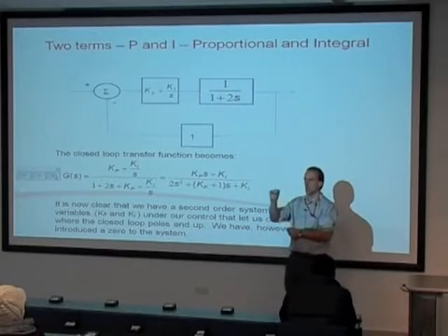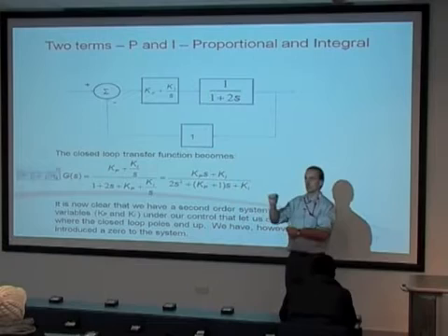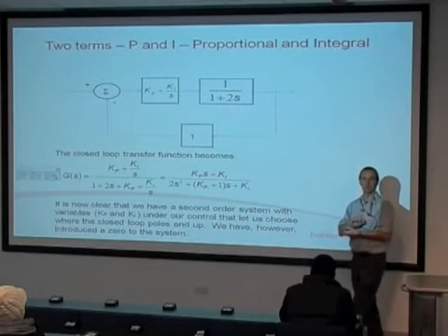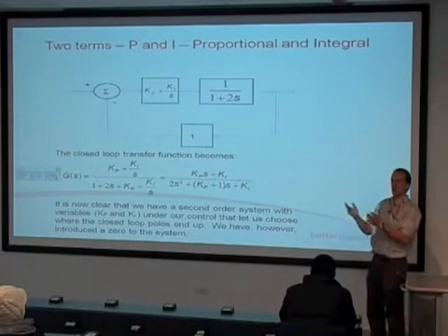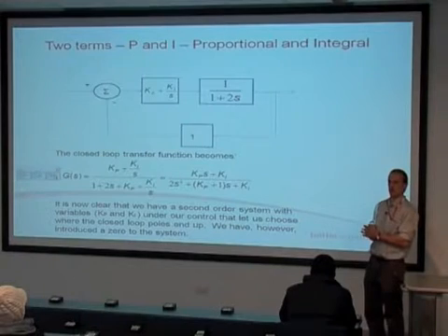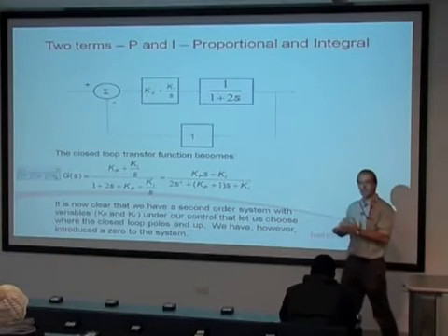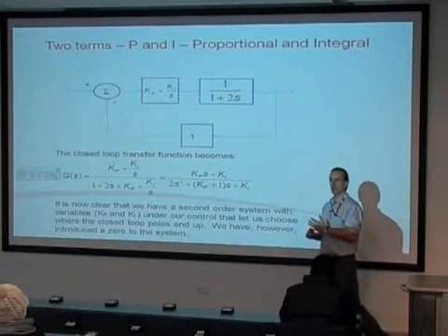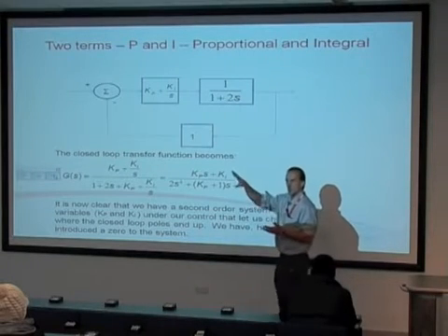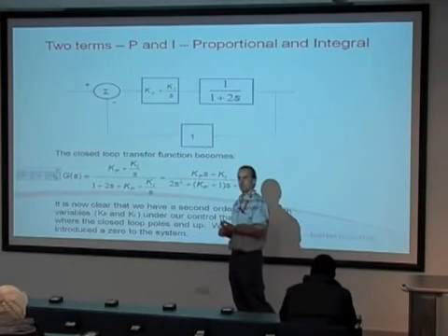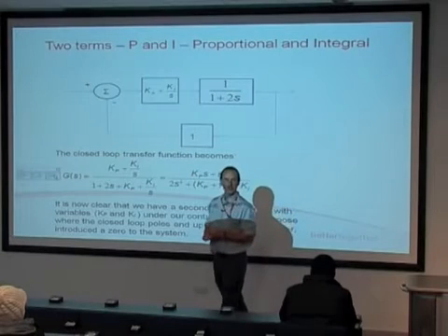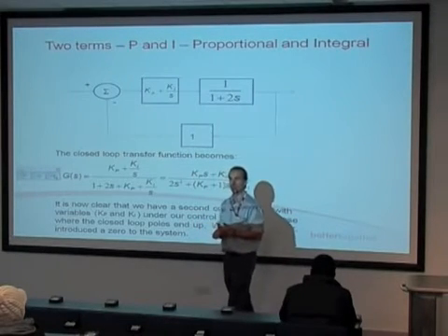So you end up with a steady state error of 1 mile an hour too slow. Let's say that's a constant of 1. If you imagine integrating that constant, what happens to the output of the integrator? If you integrate 1 with respect to time, what do you get?